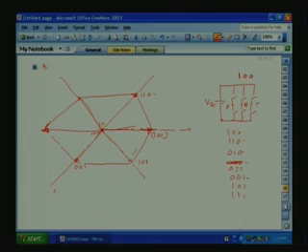Now, if you see here, see this diagram, this one is a hexagon, and the radii of the hexagon is equal to the voltage space vector structure for the 2-level inverter. Sorry, I said 3-level, but this is a 2-level inverter. That means each pole can have either plus or minus level. So, this is called a conventional 2-level inverter. This 2-level is with respect to one pole.